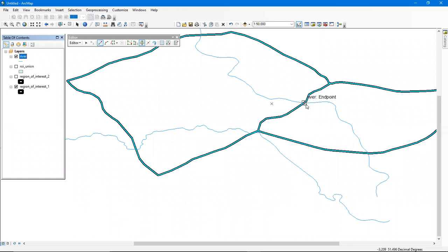This one will demand you guys know about coordinate systems because geographic coordinate systems are not used in calculating area. By default, in ArcGIS, in ArcMap, you realize you cannot use those coordinate systems to calculate the area. You have to switch to projected coordinate systems. Okay,